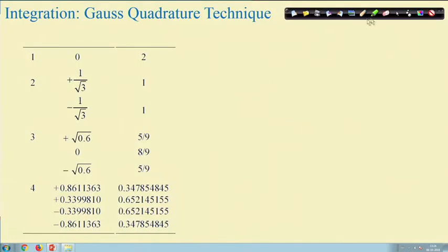All the Gauss points are defined in a parametric space, and then we have a map from the parametric space to the actual domain. That map needs to be put into the integration to get the integration over the actual domain with the information about the parametric domain. So, this is how the integration can be done in FEM.